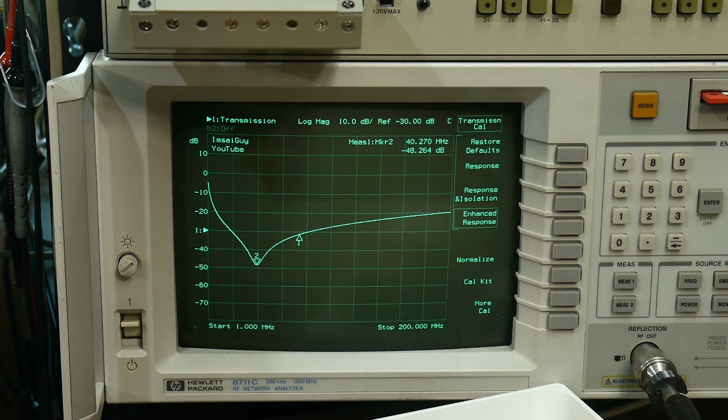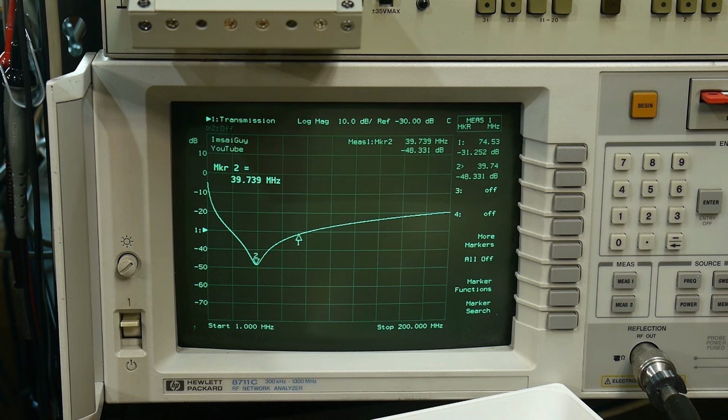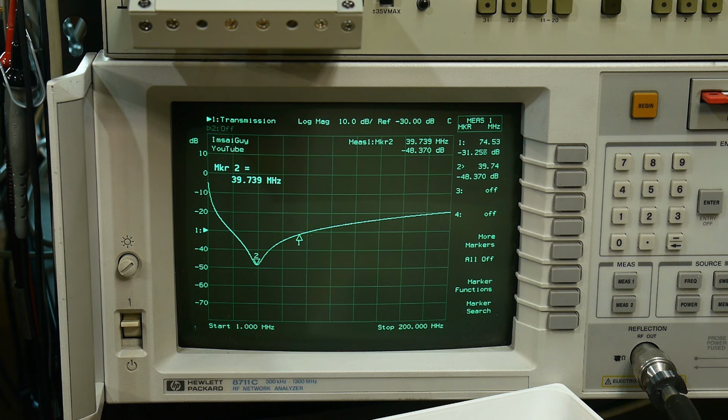So that's good, but maybe 40 megahertz is pretty high, right? Maybe we want to be attenuating a signal much lower than that, right? Maybe at 10 megahertz or something. And instead of using a 0.01 capacitor, let's put in a 0.1, okay? So let's do that next. I'll have to desolder the 0.01 and we'll solder in a 0.1. So let's wait for that.